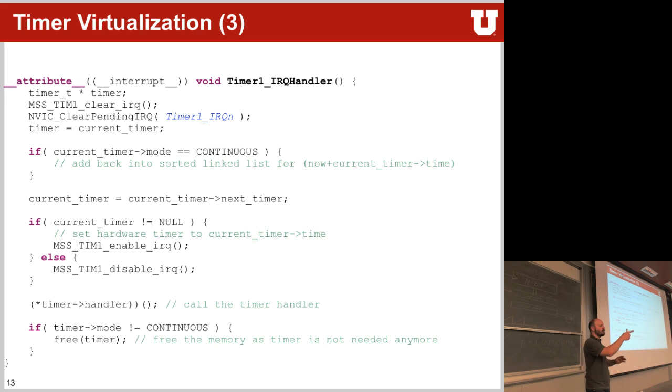Okay. Any questions to timers? Yes, before we wrap this up. Each struct adds an interrupt, right? No, there's only one interrupt that will happen all the time, right? Your interrupt is this interrupt service routine. That's your timer that will basically tell you, hey, we had a compare right now. And whenever this compare happened, you know that the top element in your linked list was the one that caused this element. So you will execute that particular event, remove it from the linked list, look at the next element, and set up your timer for that next element to happen.